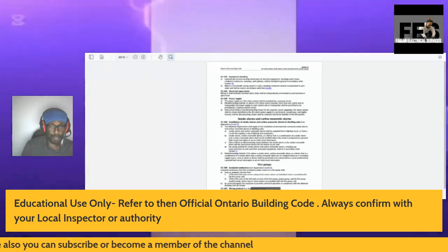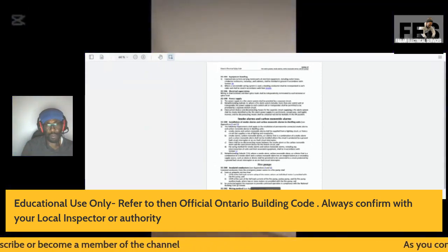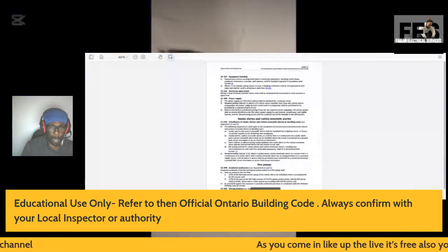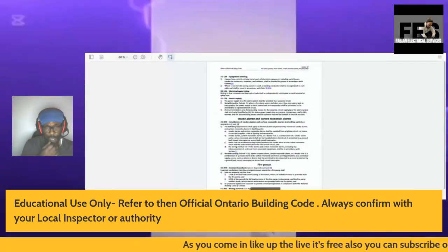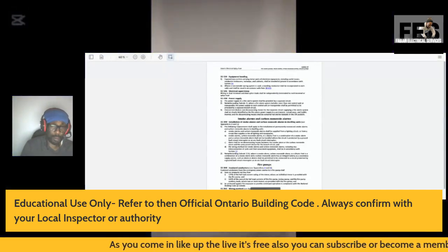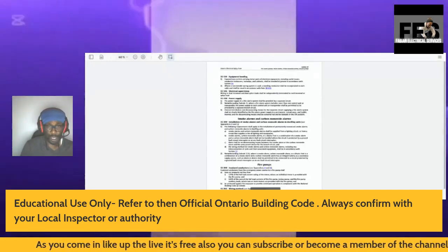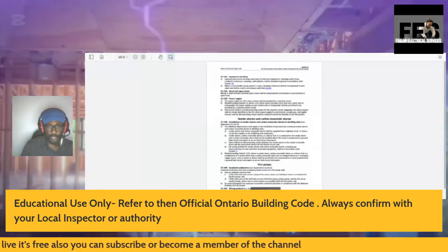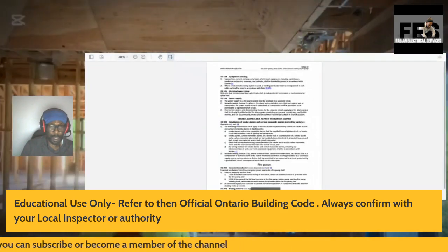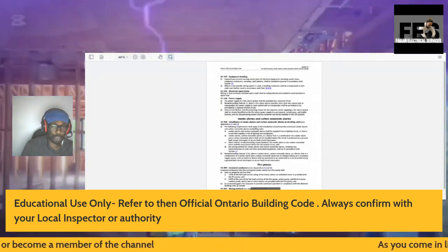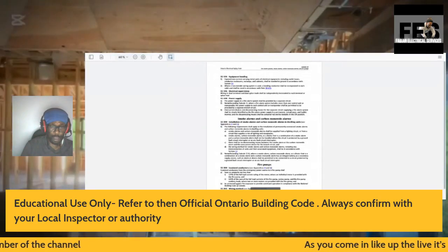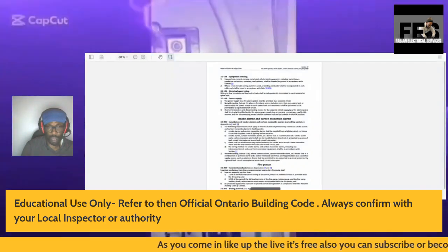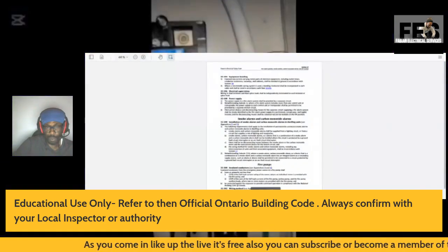If your battery is low, it will signal. Also, make sure that your smoke alarm is not expired. Max 7 years for the normal smoke detectors and 10 years for the other kind, the strobe-like smoke detectors.